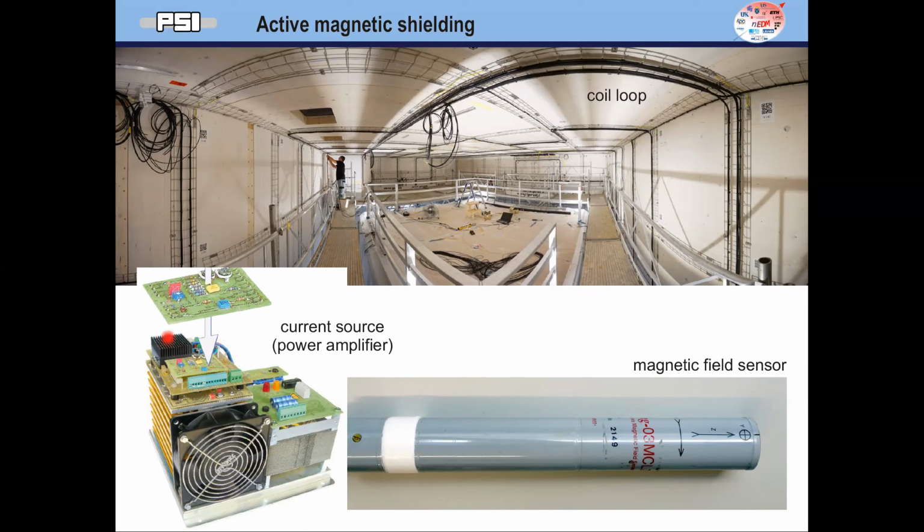But the whole function of this device is controlled by a small board where you can select which components are in the feedback path and which components are on the inputs of the operational amplifier. So exactly the same thing we've done in our lecture. Also exactly the same problems. This amplifier was unstable, and we had to add a capacitor in the feedback loop to make it stably drive the huge impedance of these coils around our experiment. So this is to give you an example that the things that we had in the lecture are actually pretty much out of the daily life in our experiment.